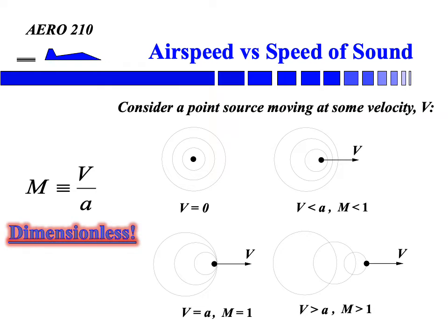If the Mach number is the same in the wind tunnel test and in the full-scale test, then we would expect that some of the phenomena that depend on Mach number would be the same in the full-scale test as in the subscale test. And this can be very useful because we can often use the results of the wind tunnel test to predict what will happen in a full-scale flight test for the same value of Mach number, for instance.